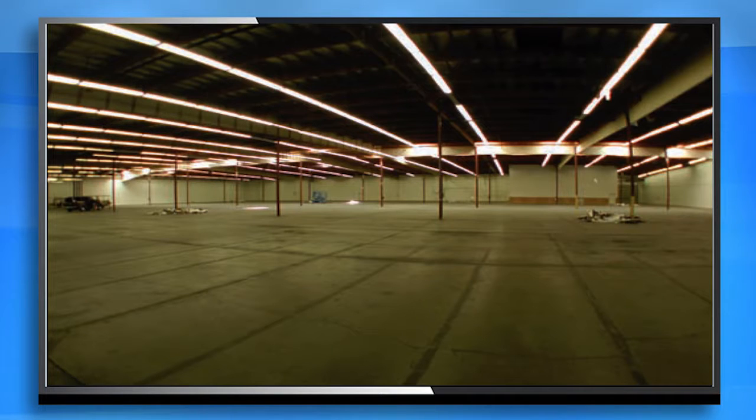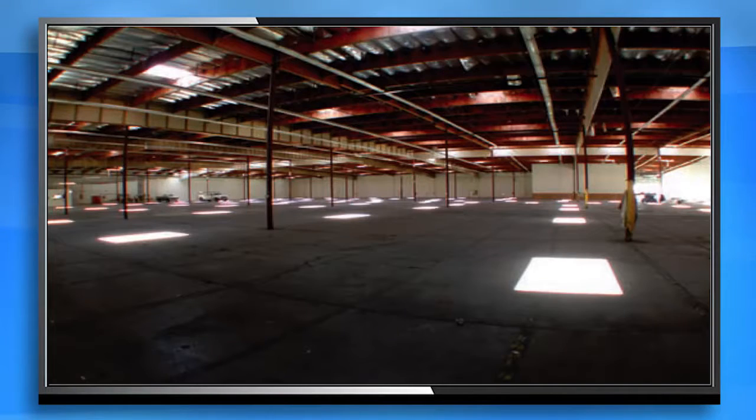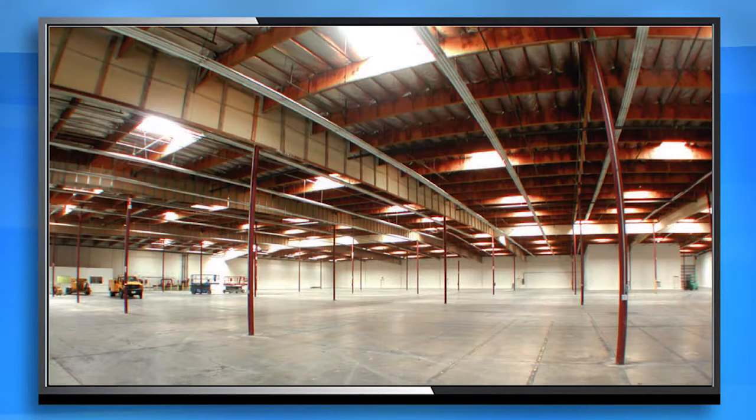Well, hey, let's put some daylight in. What do you think? Should we do that? All right, so let's go ahead and cut some holes in our roof. And then you see on the graphic now behind me that we are now having daylight. But notice that it's not very good, is it? You have hot spots. Yeah, it's not what I would really want for a daylighting project. Well, I can do better than that. Why don't I go in and put our skylights on there and now look at the space? Isn't that amazing? Isn't that great? Very evenly illuminated. Yeah, that shows you the difference between just simply putting a skylight in with great VLT but no diffusion. You have to have diffusion to get that usable light.